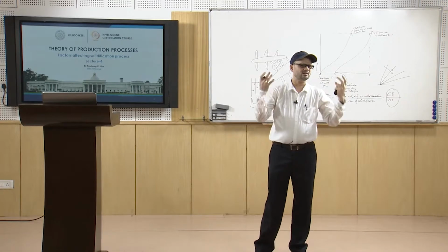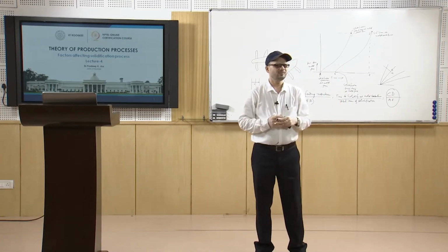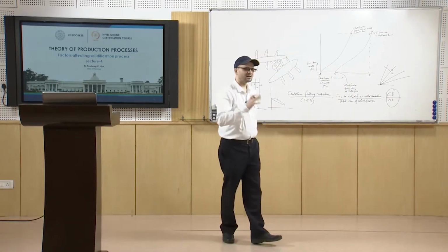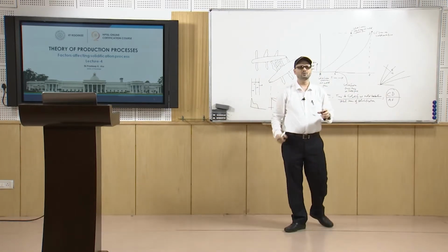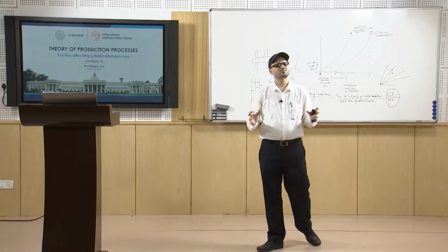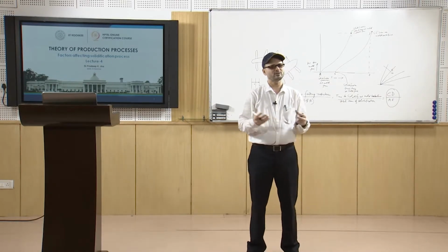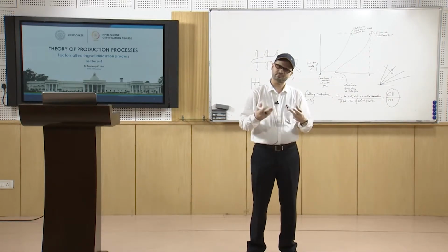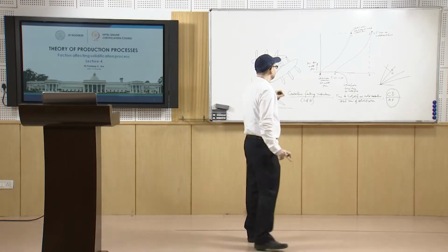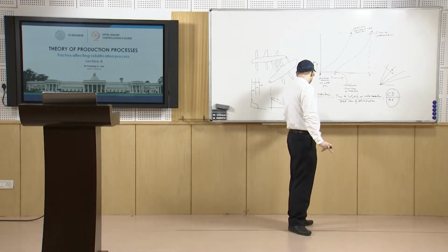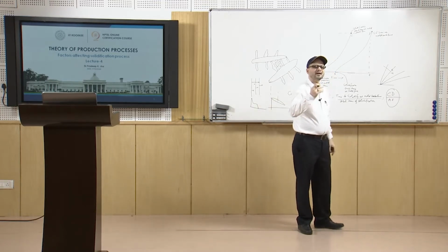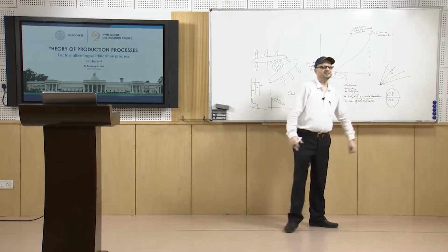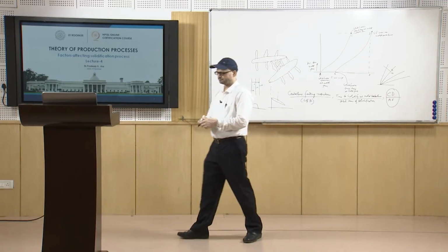There are chances that there will be a lot of defects, especially towards the center line of the casting. Whereas if it is a smaller value like 30 to 35%, it is quite reasonable, quite okay. 35 to 40%, 50% even is acceptable. So, what is seen is that this CFR value should be a smaller one, so that you can say that it is easy to feed.